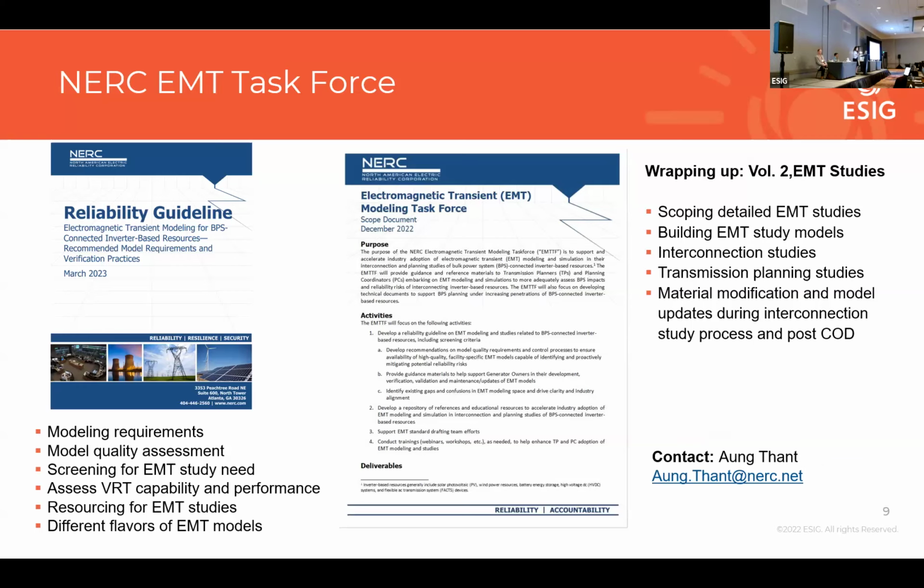I have it on the left-hand side of the slide. It's linked up there, so once you get the slides, you can go and have a look. The first volume of the reliability guideline focuses on model requirements, model quality assessment, screening for EMT study needs, and also assessment of voltage ride-through capability and performance during the interconnection process. So by having an EMT model and doing quality testing of it, you can also check some of the conformance with interconnection requirements in the area